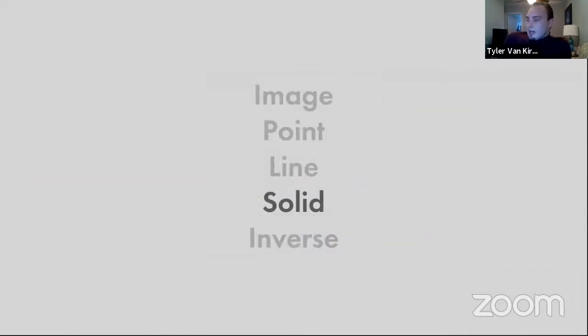And so moving on, changing that line and populating that as a solid is the next step in getting this final output. Here I'm using the low resolution image in order to have fewer lines, so the solid generation can happen more smoothly. With a higher resolution image, populating it as a solid would be a lot of data and would probably crash my computer.